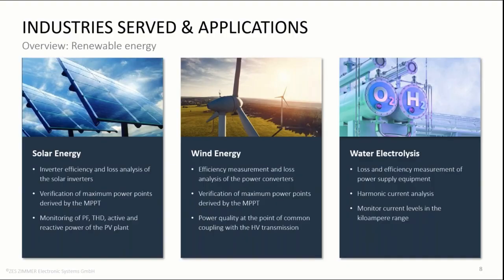The same principles, of course, apply to wind turbines, as power converters are also used there. Although maximum power point tracking has traditionally been used on photovoltaic power, it has recently been applied also to wind turbines, where the goal is to load the wind turbine just right so it delivers the most energy at any wind speed.